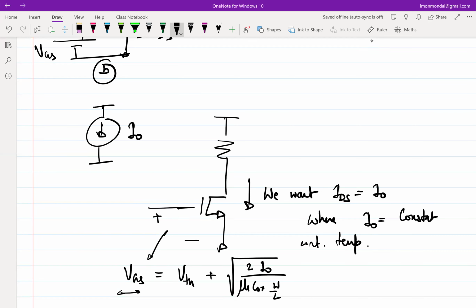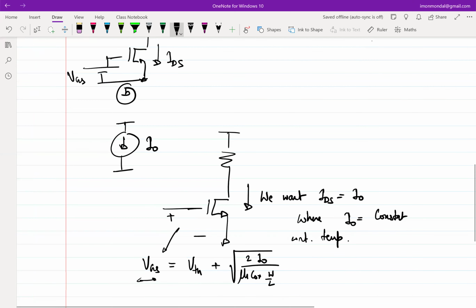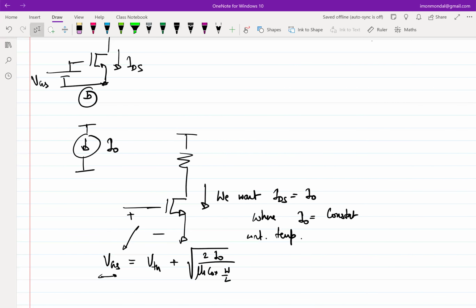So how do I develop that VGS? Let's say you can use multiple transistors. So how can you develop that VGS? Is the question clear? Okay, let me ask you this way. Let's say I do the calculation of the VGS that is required. I put a voltage source here. So is this going to work? No, right? So which means I need a variable voltage source, right? Essentially, I want a dependent voltage source, kind of, right? We want a variable dependent voltage source.